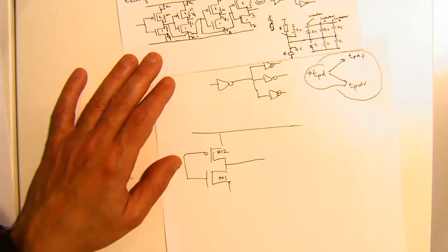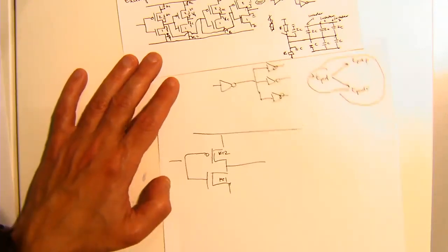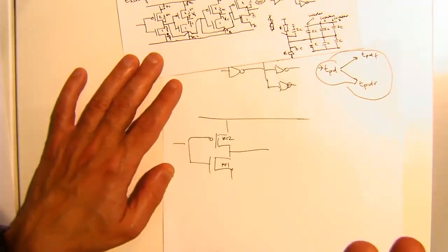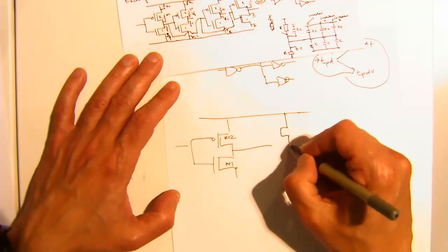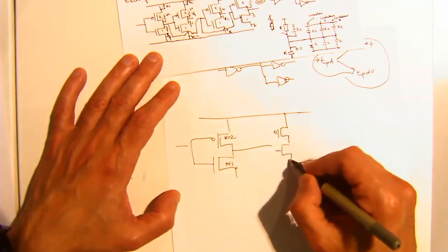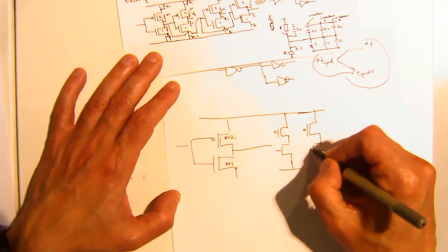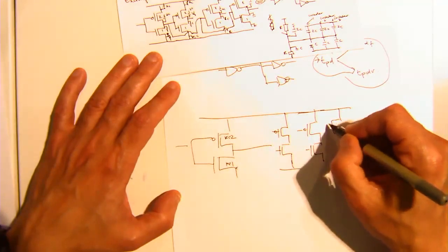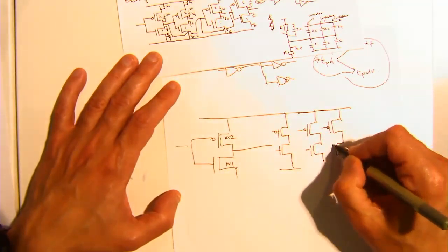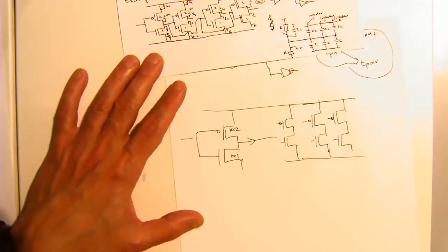Okay. So what we said is the delay depends on the capacitance, right? The parasitic capacitance in the circuit plus the capacitance that we're trying to drive, right? So what we've got here is, for argument's sake, we're driving 2 or 3 NMOS devices. Sorry. All right. So let's say I'm driving. What does this node see if it's driving through these? How is it connected?